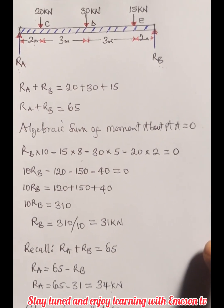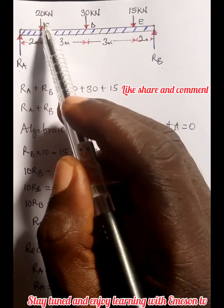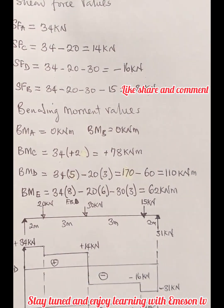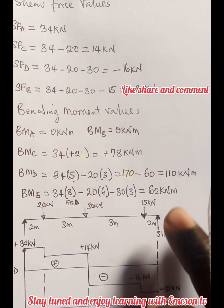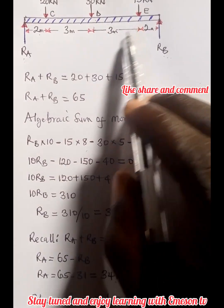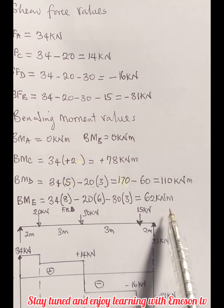So let's proceed. At point D, what is the bending moment value? The bending moment at this point becomes this multiplied by the distance 5, minus, since this force is acting down, 20 multiplied by 3. So we are having 34 multiplied by 5 minus 20 multiplied by 3. We have positive 110 kilonewton meter. So the bending moment at point E becomes 34 multiplied by the distance to the reference point, which is 8, minus 20 multiplied by 6, minus 30 multiplied by 3. That's exactly what we're going to have. So finally we'll have this.